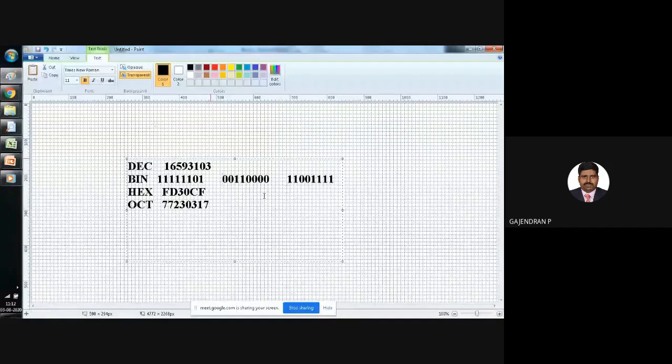See, if you compare these two, you will get the inverted value. Here it is 0, here I will get 1. Here it is 0, here it will be 1. Here it is 1, here it is 0. So in this way, we send the command value and the NOT of the command value. The remaining things are the address of the particular device.